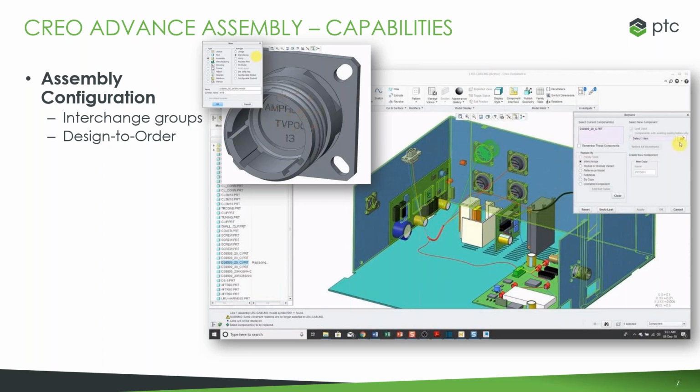So you're able to take parameters that are input by somebody. Let's say you don't just have different pieces of this. Let's say instead this dimension could change, and it could be anywhere in a range that the customer would want, right? The height and length of this. So you can have the definition of this backplate or something, or this circular cap defined by a simple program written in Advanced Assembly, or set up in Advanced Assembly, so that, let's say someone puts in a parameter and you say, great, let's have this automatically design what I need within my ranges, right?